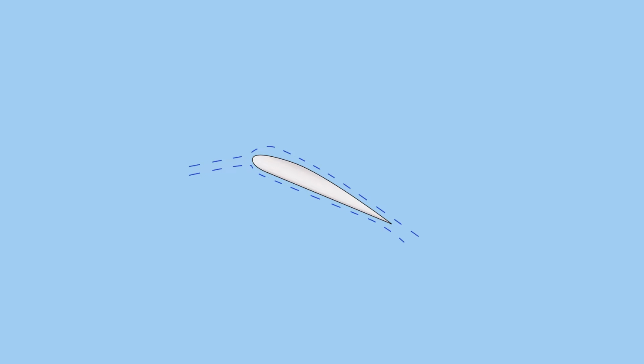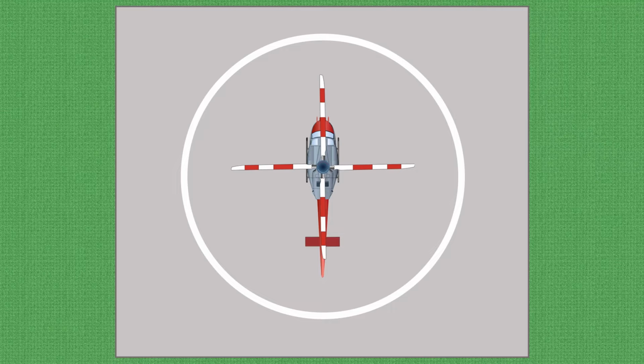The drag of a hovering helicopter is mainly induced drag incurred while the blades are producing lift. There is, however, some profile drag on the blades as they rotate through the air. An important consequence of producing thrust is torque.